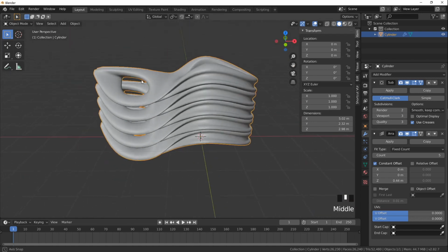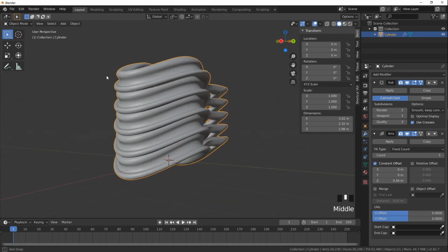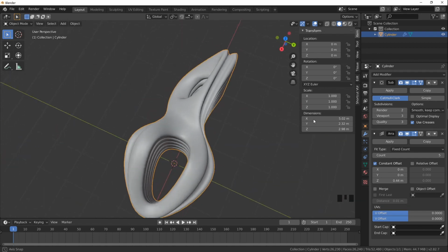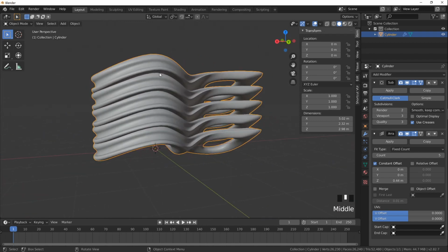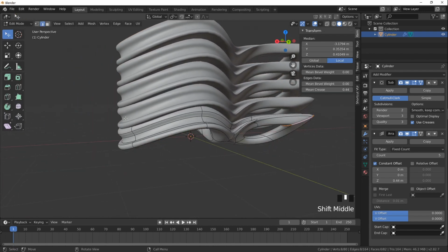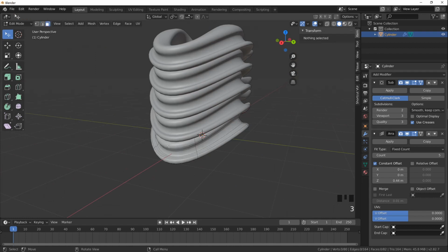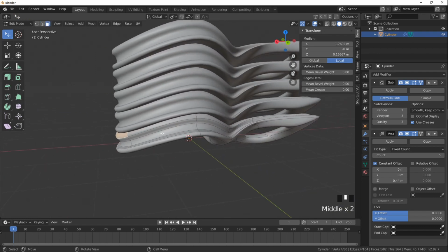As you can see, playing with modifiers allows to keep your workflow non-destructive, and you can easily manipulate and generate complexity just with simple repetition rule or other strategies. You can interactively change your object, like selecting this face and move it a little bit.